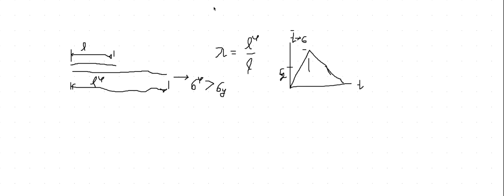So when I unload, here sigma was equal to 0. I started just applying the load. This sigma produces at any point sigma phi that is large. And then I unload here, finally, there's no sigma. I removed it. So sigma is equal to 0. Nothing going on, but the bar is no longer the same length. It has the length that I can call now LP. This is the length which became modified by the plasticity.